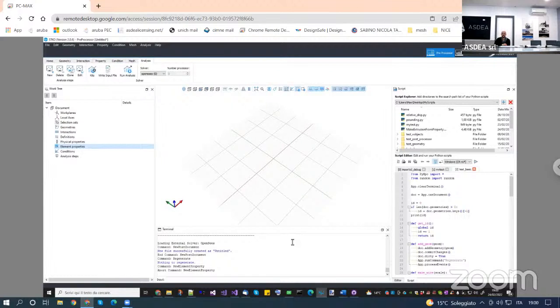And then, if all the settings are fine, you can still have problems because contact is a very hard condition. It can be either non-linear or linear, like you have a very high stiffness when you have contact and a 0 stiffness when you don't have any contact. So it can always be a problem. That's why we implemented the implex algorithm. With the implex algorithm, convergence will be much easier to achieve. So you can also use the implex algorithm for that.